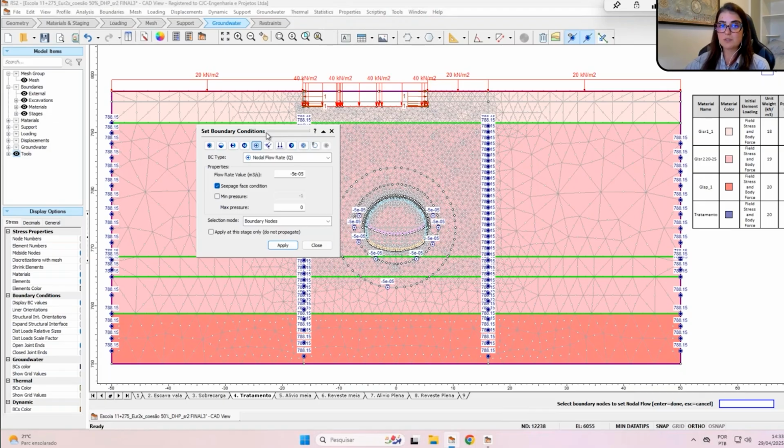So we typically treat the excavation line as a free draining phase, and the drainage devices and the external water conditions vary based on the proposed hydrogeological model. We published a paper last year discussing the influence of time on defining the radius of influence of drainage. We'll leave the link at the end of the presentation.